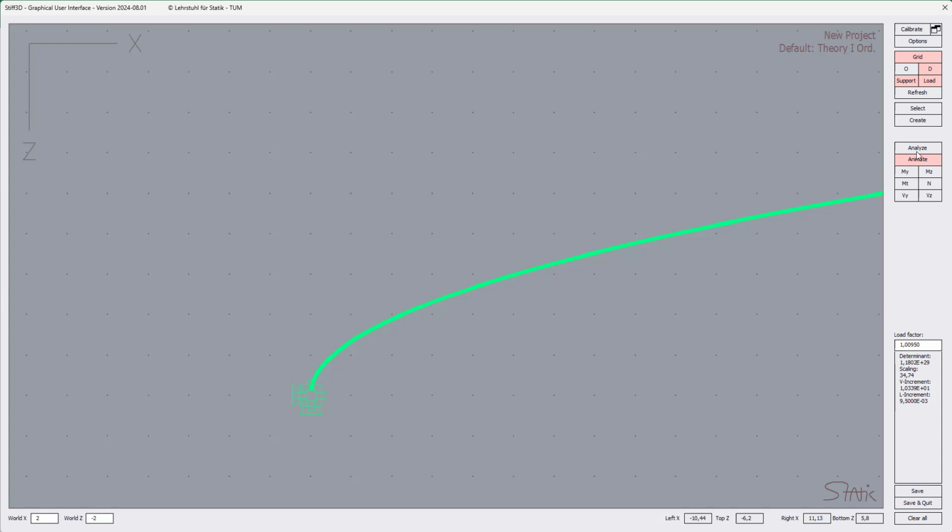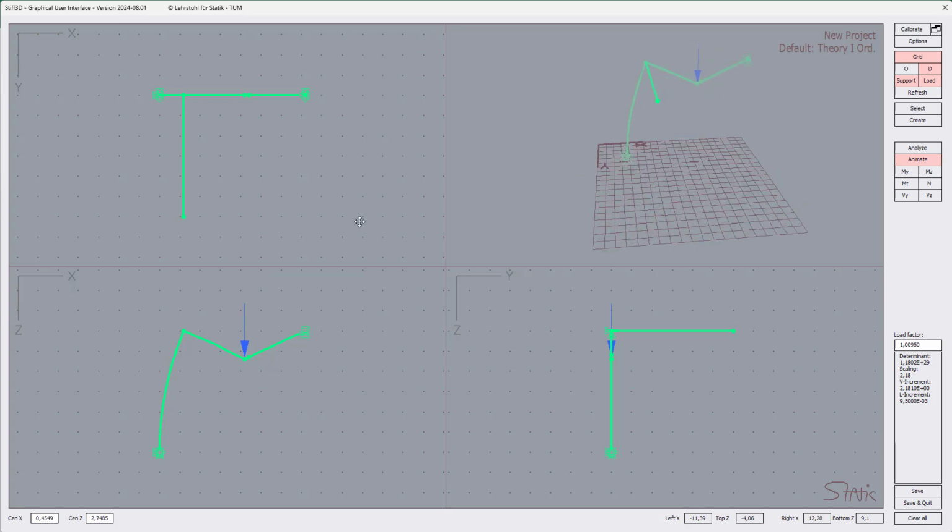The structure has become very soft. Double click on animate, and everything comes back to a reasonable display. So you see, by double nodes which share exactly the coordinates of the old node and respective degrees of freedom, we can nicely couple and decouple respective degrees of freedom. If we minimize it, we can nicely show that in the 3D graph. And I can show you that we can now really separate the hinge actions.